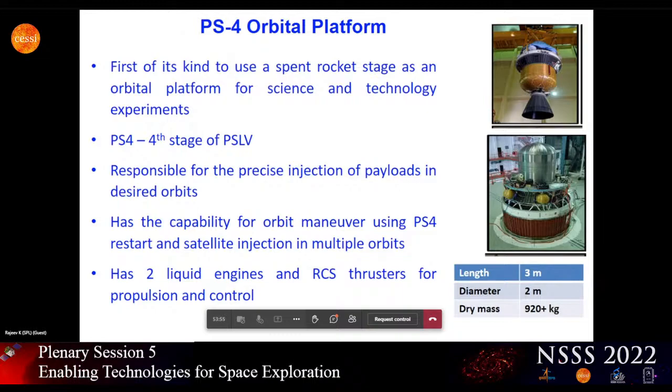The advantage of liquid fuel, I don't have to tell you, is that it can be cut off or switched on at multiple times. It has the capability for orbit maneuver, which is very important for converting it to a science experiment, including restart and satellite injection in multiple orbits. It has two liquid engines and the RCS thrusters for propulsion and control.